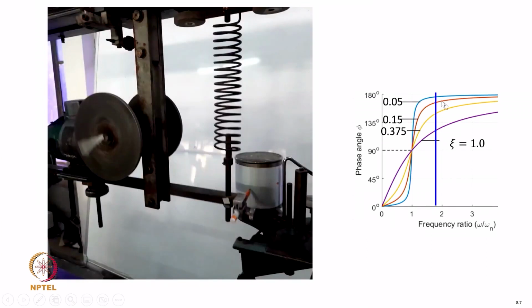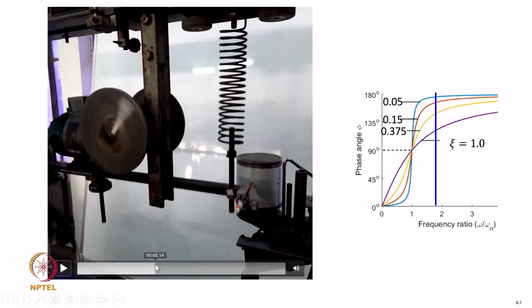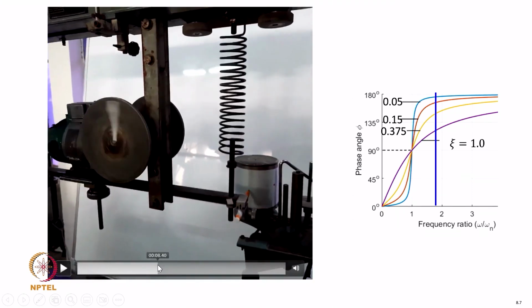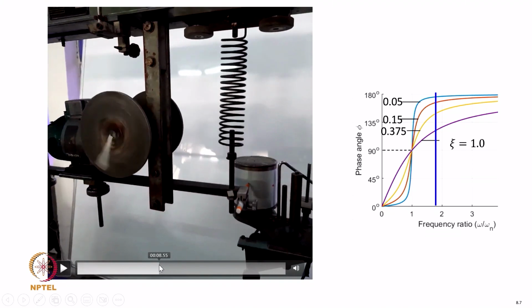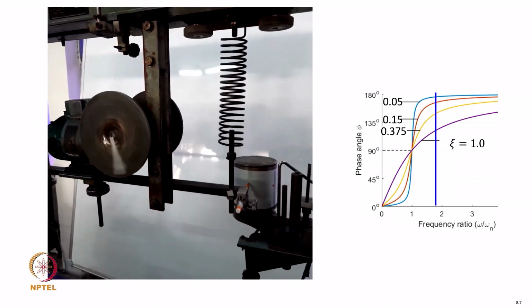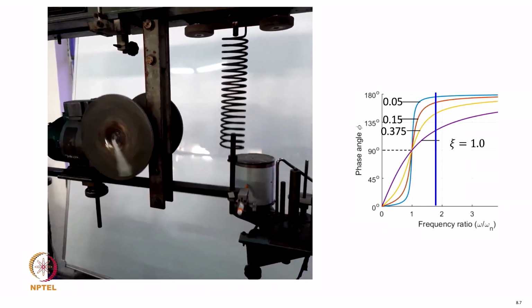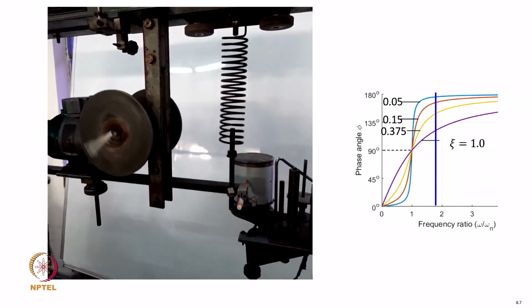In the second case, when I am operating here, which is post critical or post resonance, I will also play out this one slowly. So, you can see, as the unbalanced mass, which is represented by this white strip, goes down, gradually the pencil is going up. The mass is going down, the pencil is going up; as the unbalanced force goes up, the pencil is going down. Okay. Then as this is going down, the pencil is going up. So, you can correlate.